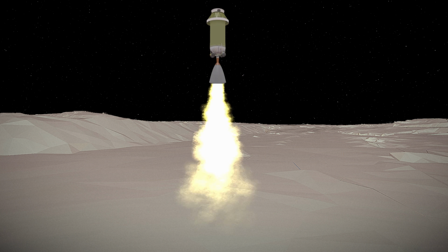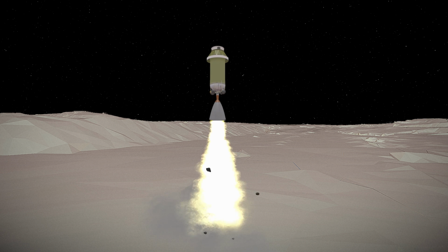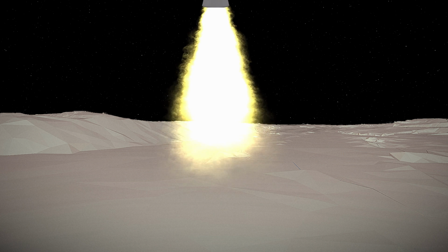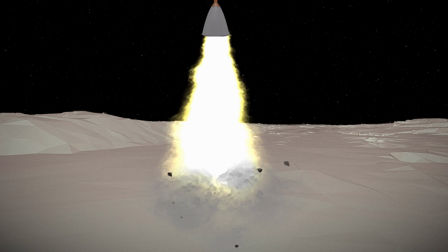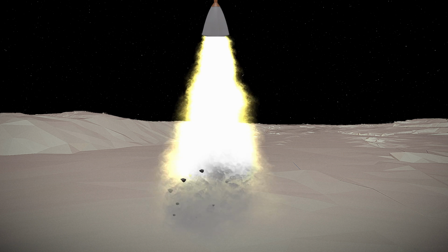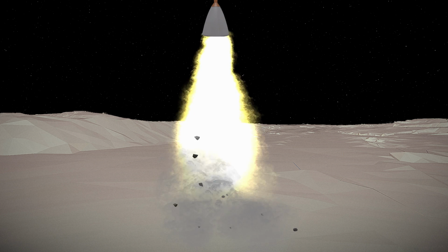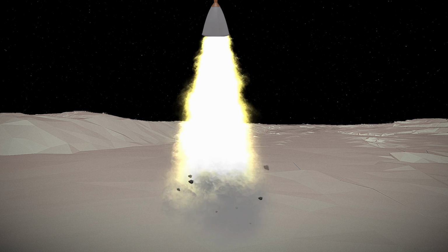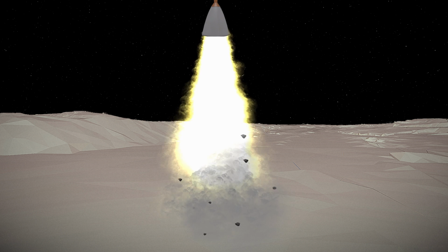Using a smaller rocket has the effect of slowing down the spacecraft at a slower rate. This, in turn, will increase the time and distance to get to the velocity needed to safely land. A smaller rocket also reduces the mass of the payload that can be carried to the surface. Preventing the rocket exhaust from getting too close to the ground means that a way must be found to get the payload from the rocket onto the surface from this minimum height. Of course, the bottom of the spacecraft needs to have some form of solid shield to protect against these debris, but the mass of the shield needs to be kept to a minimum to keep the mass of the entire spacecraft as low as possible.